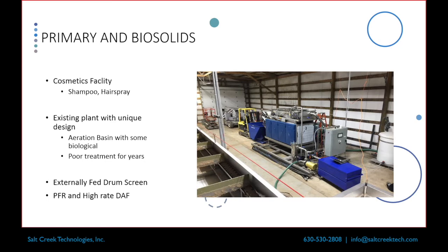We got called in for an opportunity to have a rental system there. So we installed, and you can see just the corner of it, an open style DAF to treat the biological, what was coming off the aeration basin. So we were actually lifting mostly primary solids and some biological material off of that. And then that sludge, it was generating a ton of sludge, as you can imagine, with 2,000 milligrams per liter of solids in the basin.